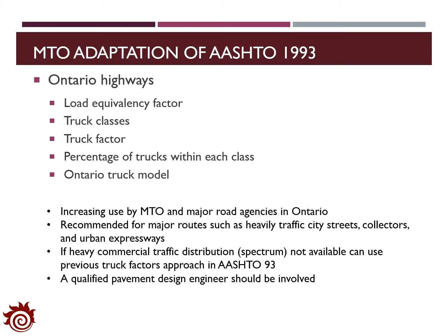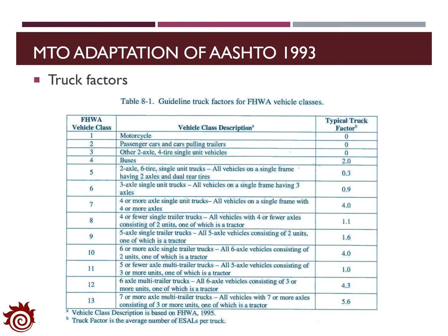In the method, if the heavy commercial traffic distribution is not available, then MTO will recommend to use the previous truck factor approach in the AASHTO method. Furthermore, MTO identified that a qualified pavement design engineer should be involved in the flexible pavement design when we use the MTO adaptation method. The table here summarizes the typical truck factors for different vehicle classes defined by the Federal